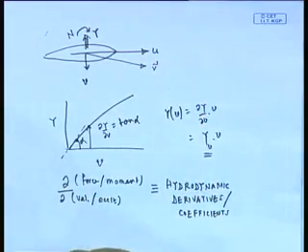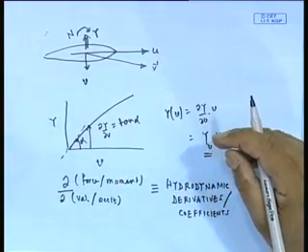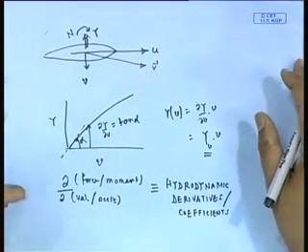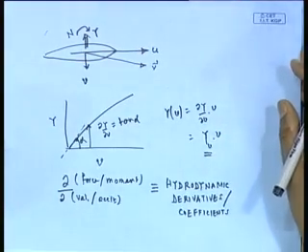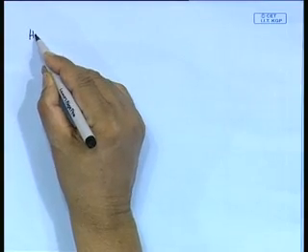For example, if you have a hull, and it was having a draft of say 5 meter, it is going to have certain KB, center of buoyancy. Now, that KB is fixed for that hull. If it is having 5 meter draft, it will have so much of KB or so much of BMT. So, that becomes a characteristic of the hull. So, hydrodynamic derivatives therefore